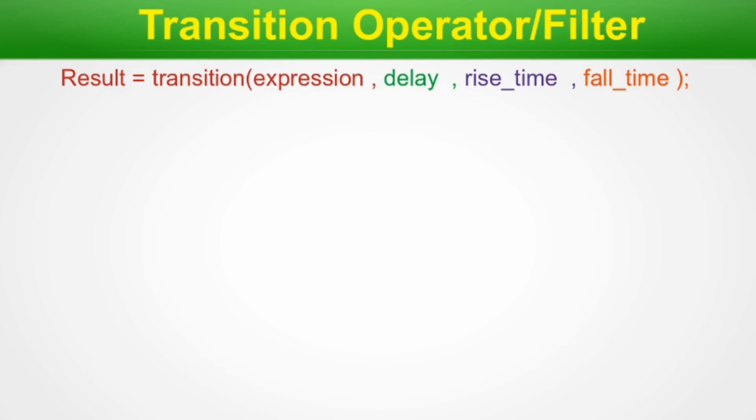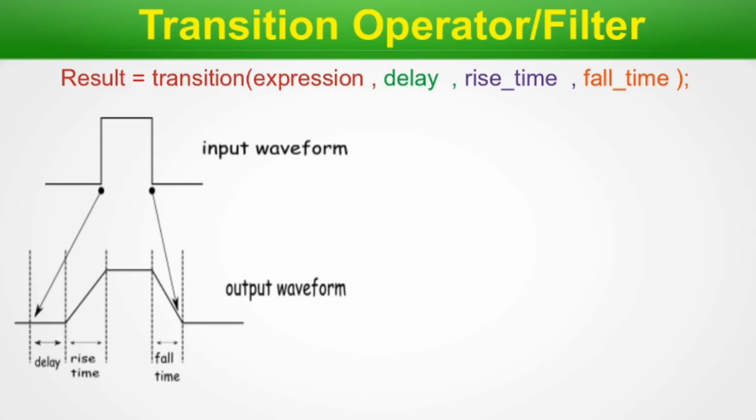So this way we will define the transition operator, and let's look graphically how this thing will impact. The top waveform, here we bring the mouse pointer. This is the digital waveform. Here we see it is sharp changing, then it is flat again coming down. So this node, if we add a delay, it will shift here. This is the time shift, or the delay that is added.